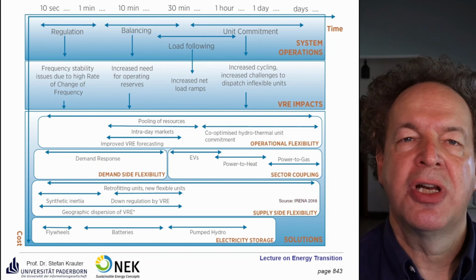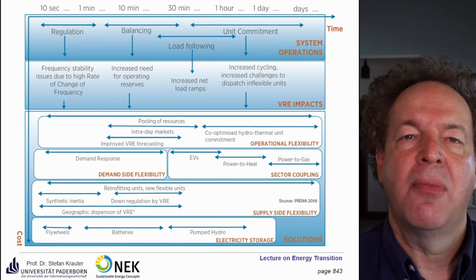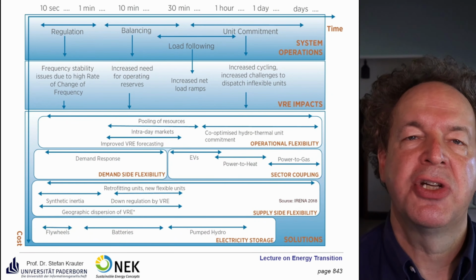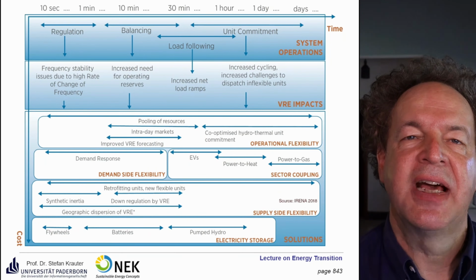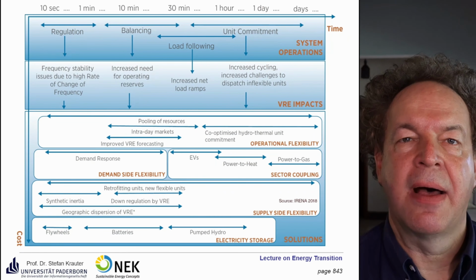So what you do usually, you rectify it, make a DC current out of it, and then electronically convert it into AC current. So there is no flywheel anymore, so there is no inertia anymore, and therefore you cannot count on this inertia. Therefore, you have to provide some synthetic inertia.